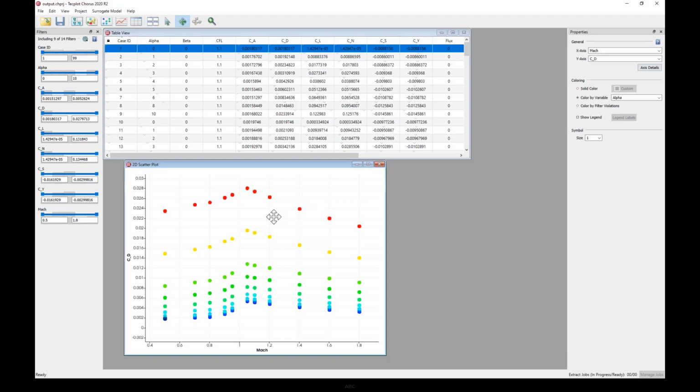And what we can immediately see here is that we get a spike in drag as we cross over Mach 1. So we can see, okay, things are pretty nominal here. We're probably getting some shock, which is causing the drag, and then the drag starts to taper off. So immediately you can see that we have a pretty well-performing vehicle here. So nothing to be worried about, but we have seen many aero databases where you have an outlier.